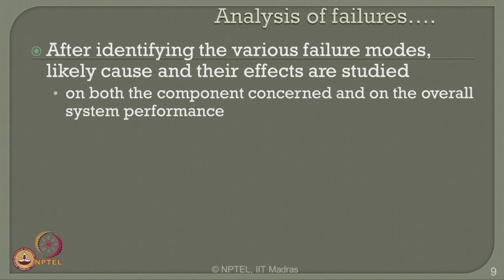Now, dear friends, you will know that FMEA is purely a risk analysis method because it also tells me the probability of failure modes. In addition to that, it also gives me the consequences or the effects of these failure modes, and we know that risk is generally the product of these two. So, FMEA is one of the quantitative risk methods which analyzes risk in a given mechanical or electrical system with a focus on the subsystem or the components in a given global system. It essentially focuses on the components concerned and the consequence of the failure on the overall performance of a given system.